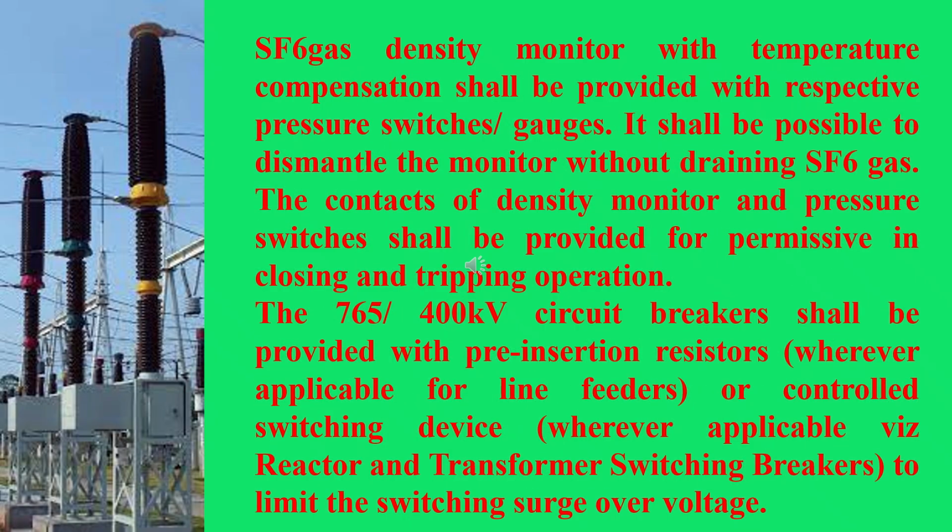SF6 gas density monitor with temperature compensation shall be provided with respective pressure switches. It shall be possible to dismantle the monitor without draining the SF6 gas. The contacts of density monitor and pressure switches shall be provided for permissive in closing and tripping operation.